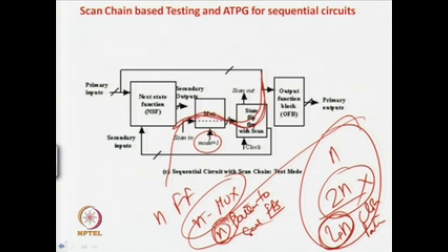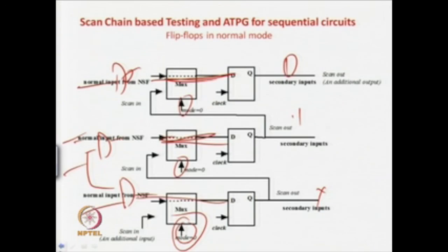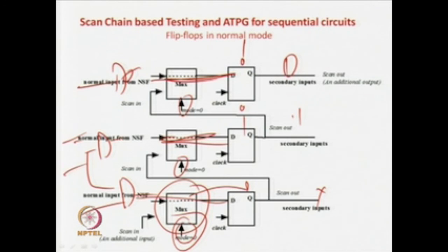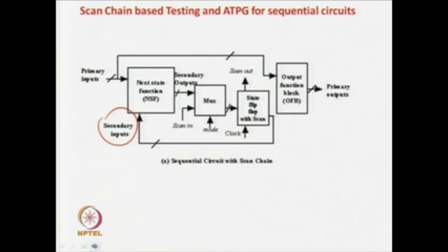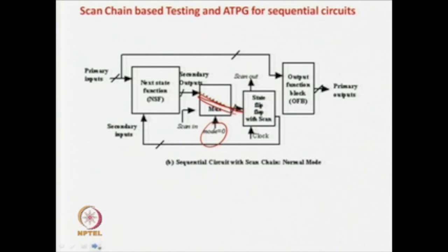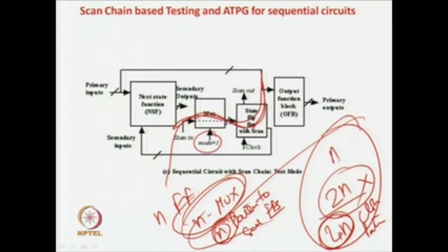And also you have to observe one thing, that here flip flops do not require a set and a reset line, you are doing it in the normal way. So, the flip flop size can also be made smaller than the set reset flip flops. If I have a flip flop with set and reset signals, then the area will be larger than a flip flop which does not have a set and reset line. So, the flip flop with a set reset line is almost equivalent to a flip flop with a mux. In fact, this additional mux is not at all a problem. The n muxes we are adding, that area we are also saving by not using any kind of set reset flip flop. That is another very great boon we are getting, correct.